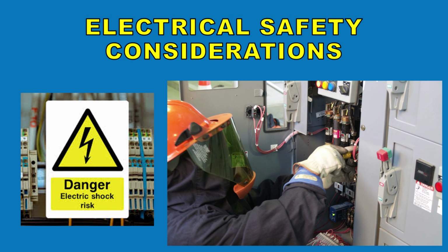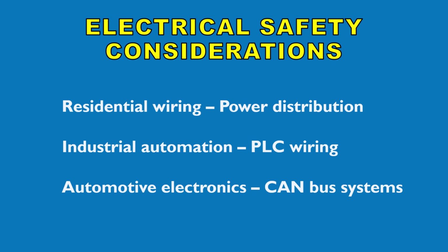Adherence to electrical safety protocols is imperative. Always de-energize circuits before performing maintenance, verify insulation integrity, and comply with OSHA, Occupational Safety and Health Administration, or IEC regulations. Wiring diagrams are extensively utilized across industries, from residential installations to advanced industrial automation systems and automotive control networks.